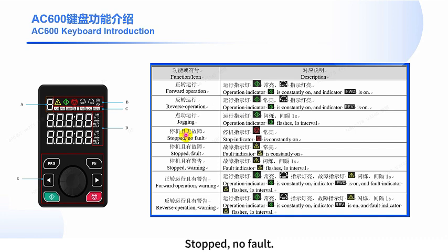Stopped. No fault. Stop indicator is constantly on. Stopped. Fault. Fault indicator is constantly on. Stopped. Warning. Fault indicator flashes, 1 second interval.